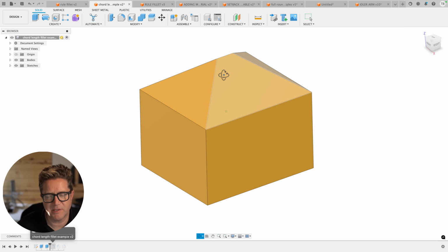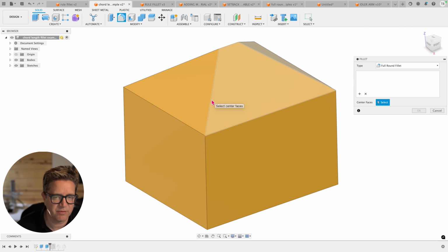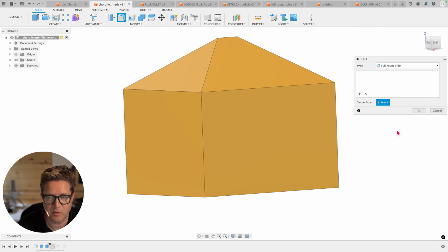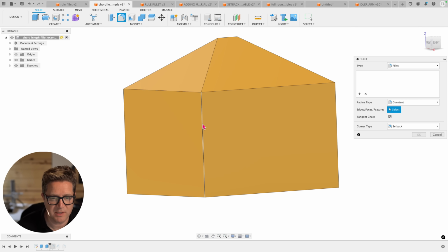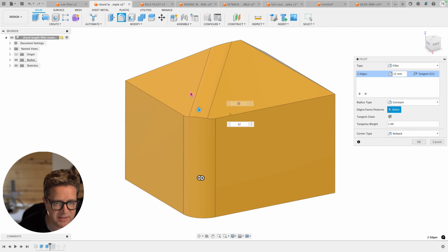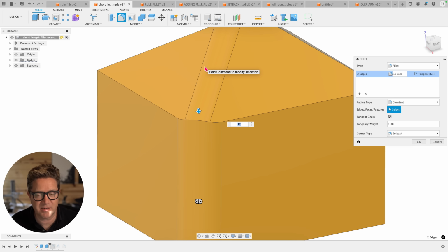One challenge you're going to bump into with fillets is when you have a transition between angled faces that have a very different angle. For example, these have a pretty steep face, and this is a 90-degree angle between these faces. So if I were to go to my fillet command, choose this one, even though the radius is 12, you'll see they have a very different solution in the width of the fillet based on these faces that it's solving between. And this tip comes from Matt Perez over at Everything About Design. I'm a huge fan of his channel, very cool content.